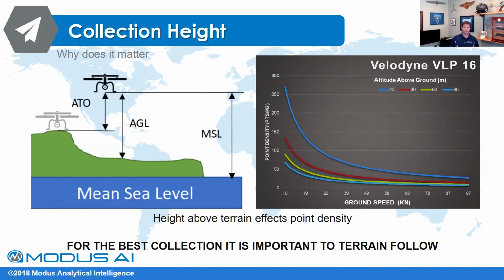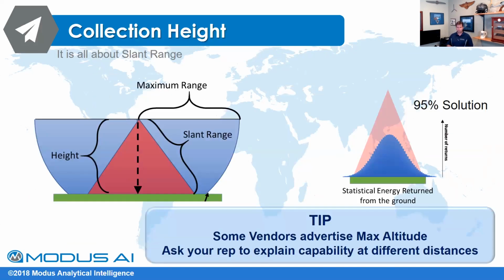The second part is altitude, which is efficiency. So going to the next slide here, when we're doing, say, photogrammetry, you're going to have a footprint below you, and that footprint is going to dictate how much area you're covering. Typically I use a field of view of 90 degrees, unless I'm getting into more advanced stuff. That allows me some very simple math: my altitude times 2 is going to be my swath width. So if I'm at 100 feet, my swath width is going to be 200 feet. And then I take 10% off for overlap.